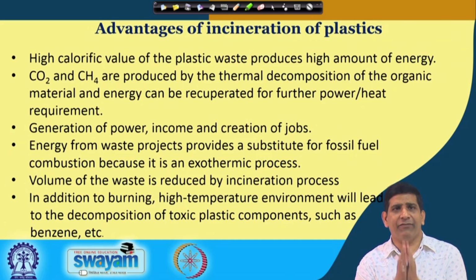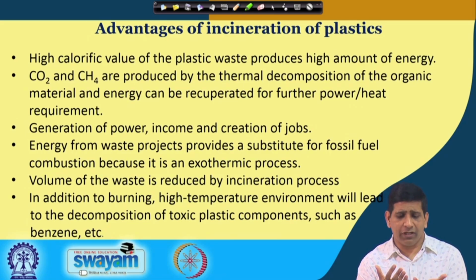Now, what are the advantages of incineration of plastics? It's the high calorific value. Plastics essentially come from crude. They are petroleum based products. Since they are petroleum based products, they have a high calorific value. So that helps in producing a high amount of energy. And when you do this destruction, you will have thermal decomposition of organic material. You have CO2 being produced.